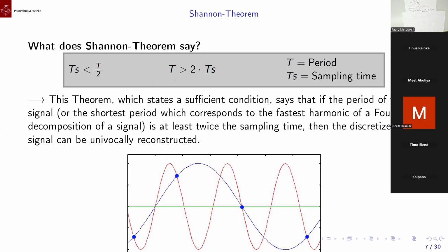In any case, if it's guaranteed, we can reconstruct the signal. We can calculate univocally the function which meets all points, or univocally the approximated regressor, because the problem is convex, must be convex in the sense. The other problem which we have is very often Ts is not constant, like here. The distance here, Ts1, Ts2, they are constant in the formulation of the theorem. The theorem gives sufficient conditions.